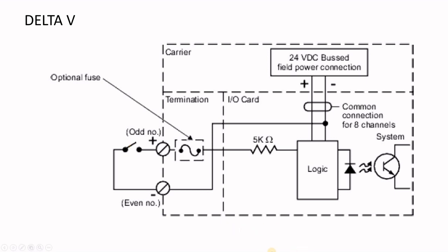Here they put something and they call it optional fuse. In fact, this fuse will not act as a fuse for protection, because if you close the limit switch, you will run everything through the wire as if it is a short circuit. That means this will never blow the fuse unless you have a higher voltage, and then you will have more current here.